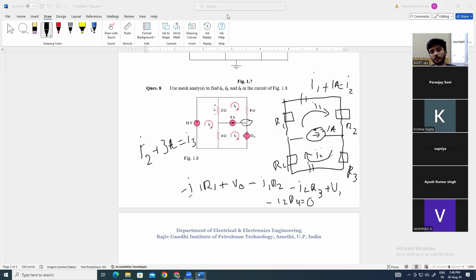Yes, very good. You can also unmute yourself and just write the same. Since we already have two equations and just two unknown variables, we would be able to find I1 and I2. And we would not fall into the trap that, since the current source is in the middle, if we just try to apply KVL, both currents come out the same. No, we don't do that.